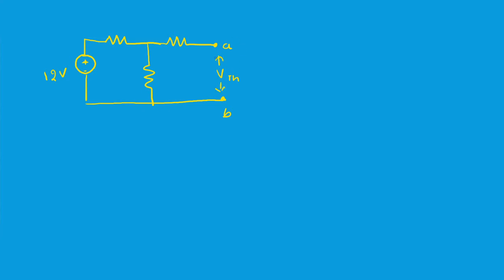When I'm open circuiting this, whatever the resistor here is doesn't matter for us, because the current flowing through it is going to be 0 since it is open circuited. Yes or no? Whenever this is open circuited, no current flows here, so we are not bothered about it. If you want to find the Thevenin's voltage, it is enough to find the voltage across this. I think it is given as a 3 ohms and then a 6 ohms, right?